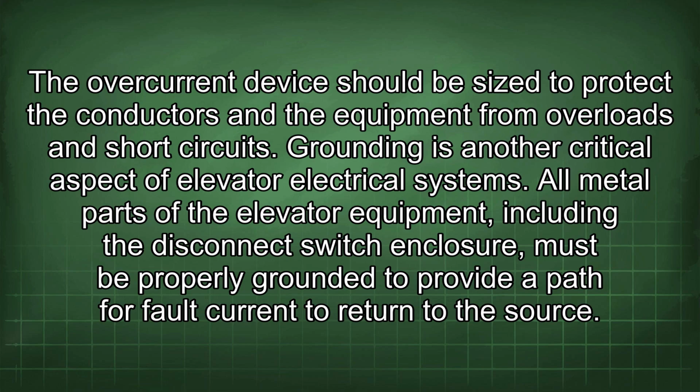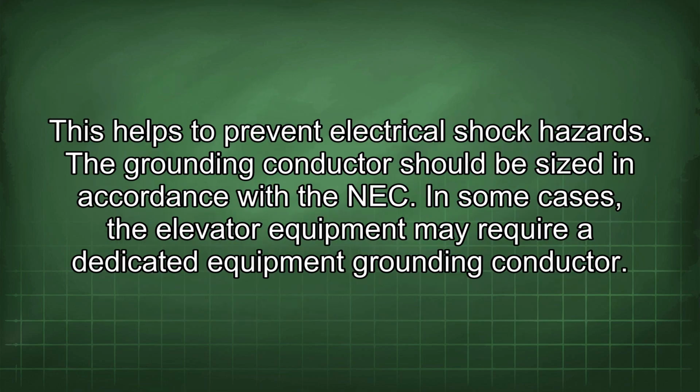Grounding is another critical aspect of elevator electrical systems. All metal parts of the elevator equipment, including the disconnect switch enclosure, must be properly grounded to provide a path for fault current to return to the source. This helps to prevent electrical shock hazards. The grounding conductor should be sized in accordance with the NEC.